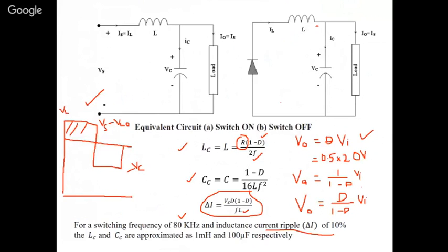The current also they have discussed two things. The inductor current goes on increasing. After reaching this point, when the switch is turned off, it decreases, and again it increases. So this is said to be continuous conduction mode. In continuous conduction mode, the current will not become zero.